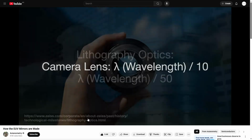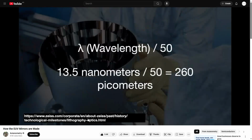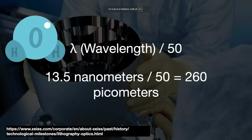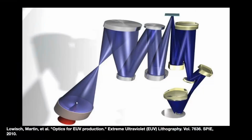An advanced lithography optics system must limit its wavefront error to something like lambda divided by 50. So in the case of EUV lithography, where the wavelength is 13.5 nanometers, we take 13.5 nanometers and divide by 50 to get 260 picometers. To put that into context, a water molecule, just one, is 275 picometers wide.